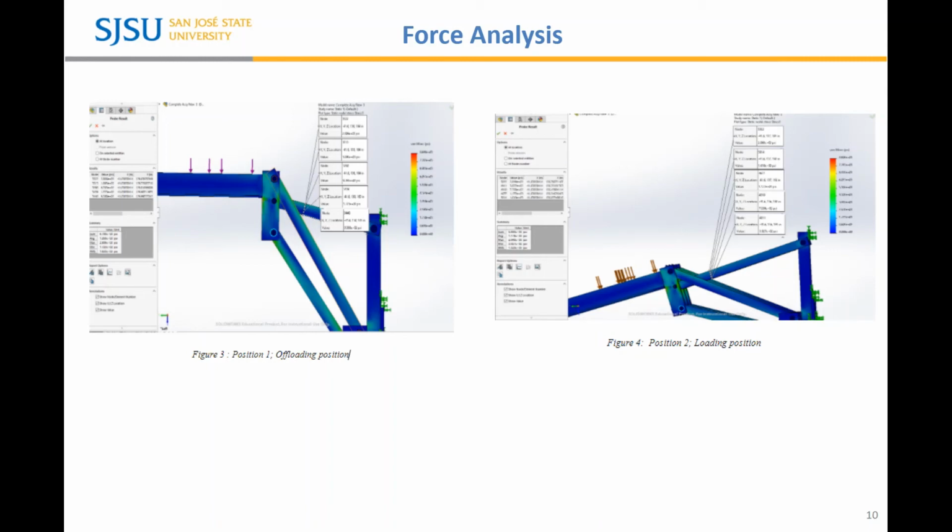The force calculations for the ramp were done in its lowered and topmost position in order to get a clear understanding of when the winch would have to endure the maximum amount of force. Using SOLIDWORKS, the probes were placed across the cross-sectional area of the steel bar, which computed the average stress that would be exerted on the winch. Then, the average stress was divided by the cross-sectional area, concluding forces exerted on the winch for both positions. Based on these calculations, the maximum force of 1,086.4 pounds was determined.